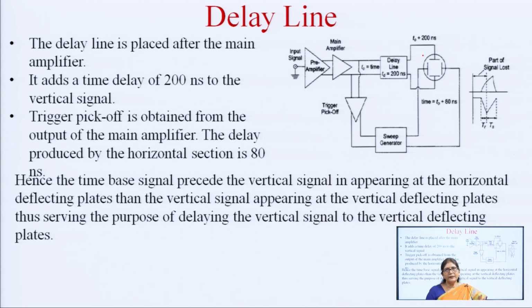Hence, the time base signal precedes the vertical signal in appearing at the horizontal deflection plates, and then the vertical signal appears at the vertical deflection plates, thus serving the purpose of delaying the vertical signal.